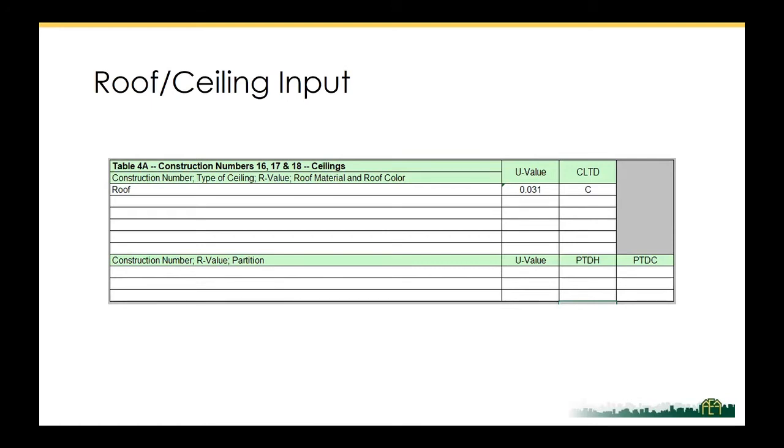You have construction details that also increase the R value. And I think also most attics are loose fill fiberglass, and loose fill fiberglass is a little bit easier to achieve QII than actually having batt.